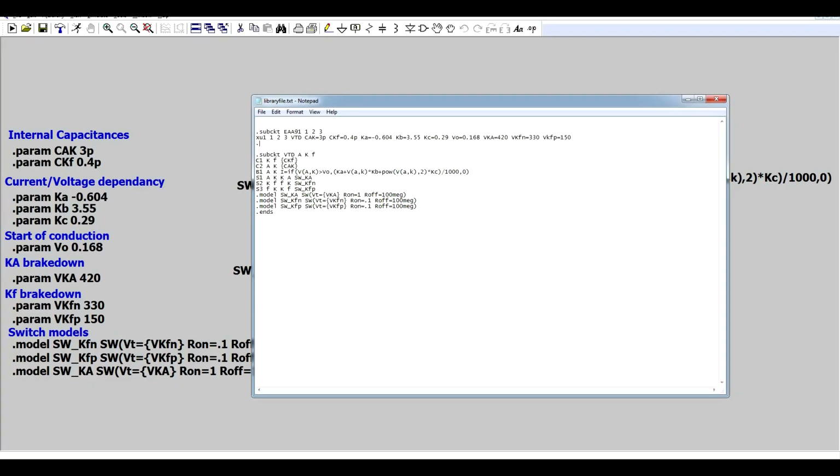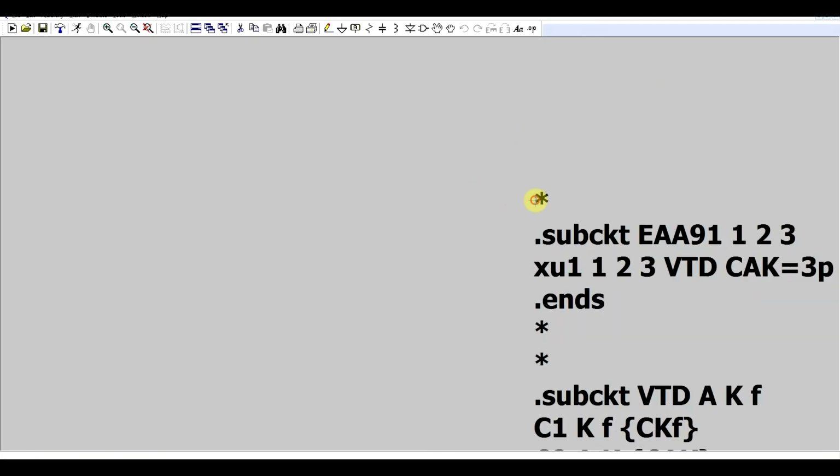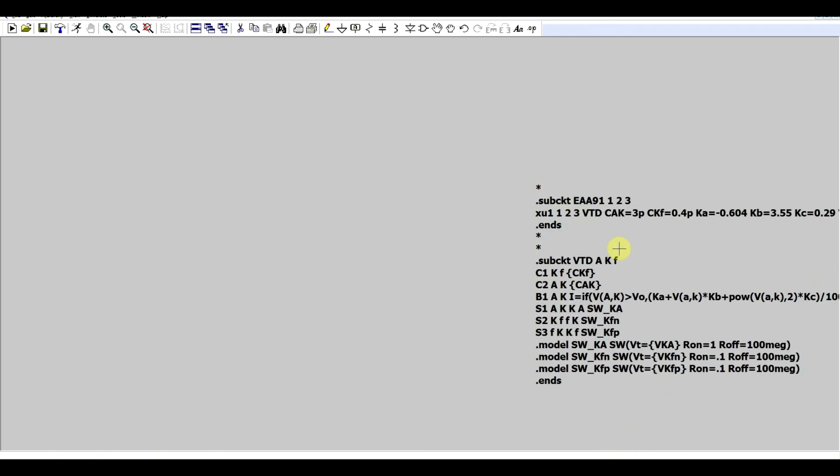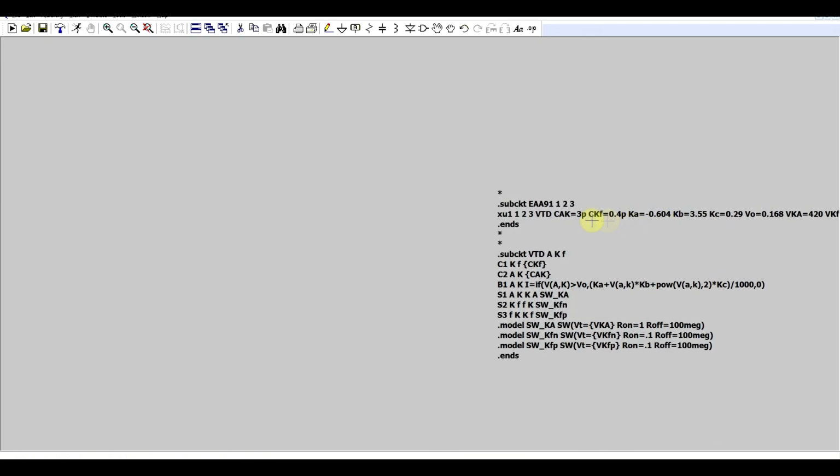We'll need to end everything with, again, an .ends command, maybe add some spaces in between just to make things a bit clearer. And now basically our library file is done with one component. So how do we test it? Make sure that we didn't make any mistake in the process. Well, we can import everything into a SPICE statement, we can include it as a library file, but it's still not really useful at this point.